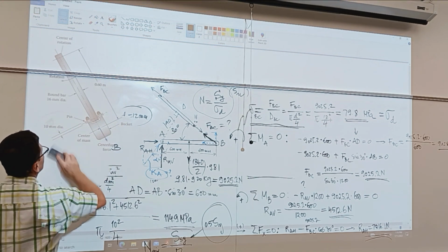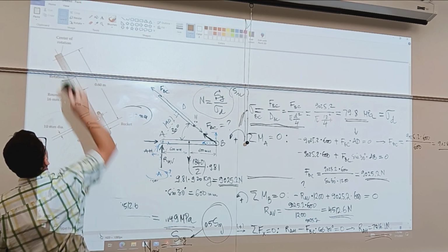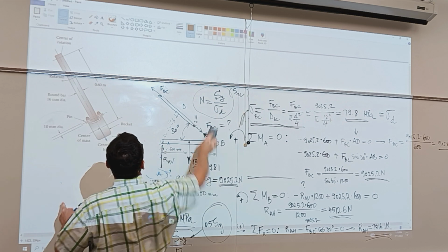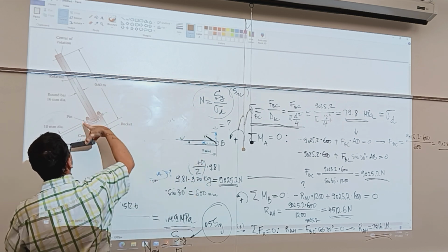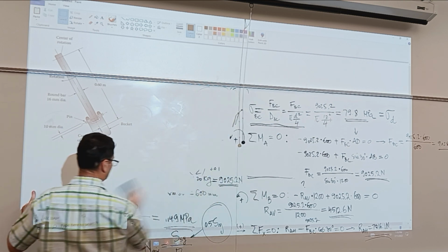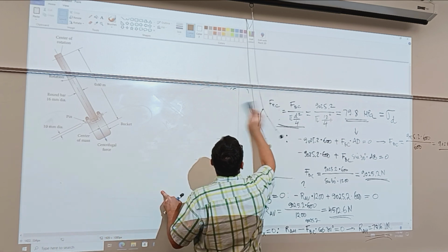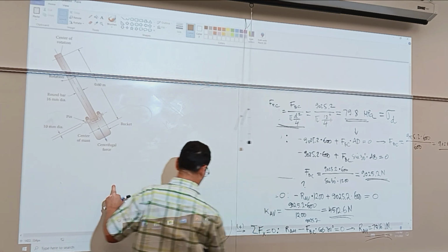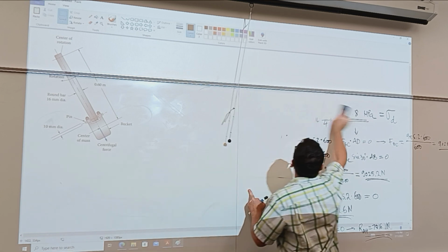So the centrifuge arm rotates about a vertical axis in the horizontal plane. The force that loads the pin in double shear is going to be the resultant of the weight of the basket and the centrifugal force.